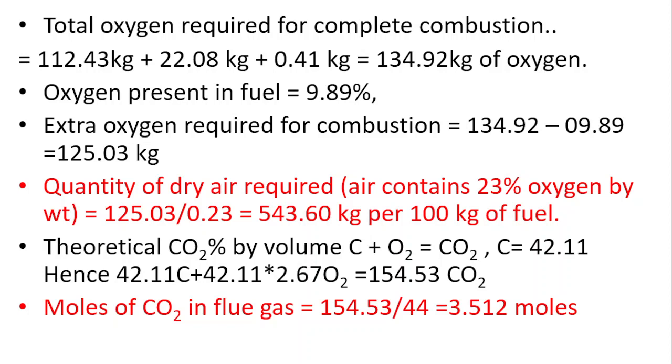Now there is some oxygen present in the fuel as per the ultimate analysis, and so the extra oxygen that will be required for complete combustion would be 125.03 kg. The quantity of dry air that will be required, because air contains 23% oxygen by weight, will be around 543.60 kg per 100 kg of fuel.